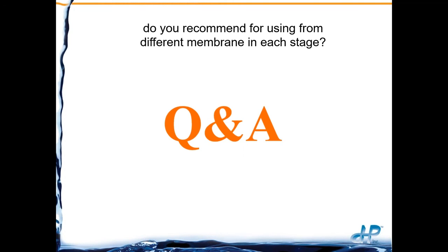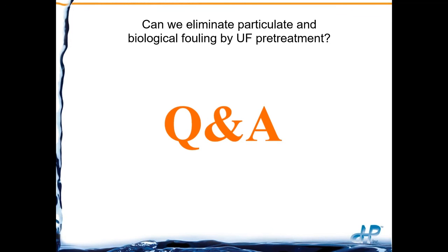Basically, the goal is to actually get more water passing through the second stage than the first stage, so it reduces the fouling potential of that first stage. You basically have to do an analysis using the membrane manufacturer's design programs to see what's going to work best for you with these hybrid type systems. If you're interested in something like that, we'd love to help you. We also will help with the technical services aspect of that. Give us a call.